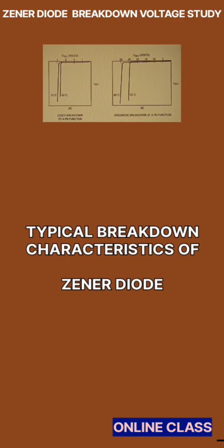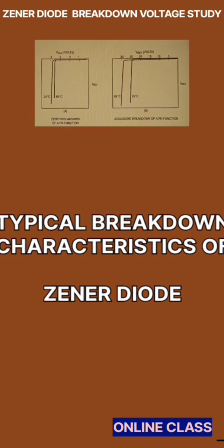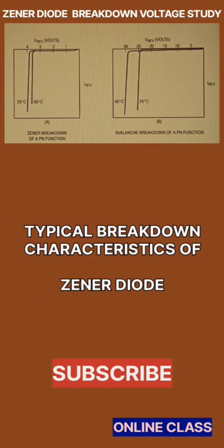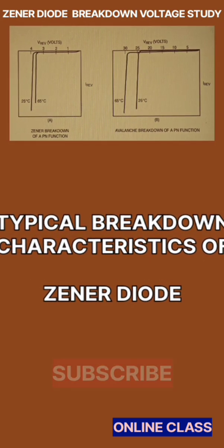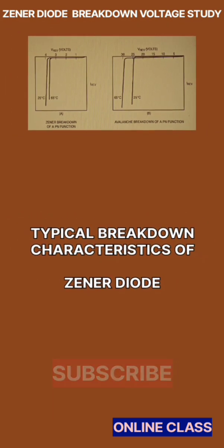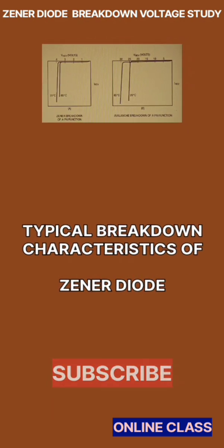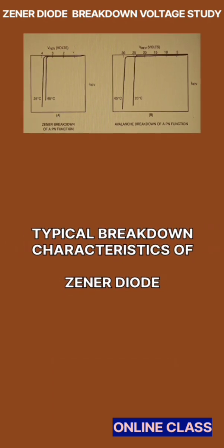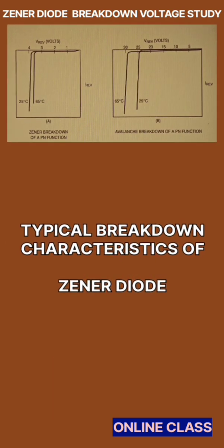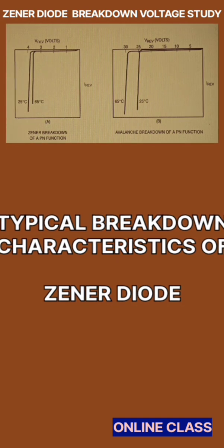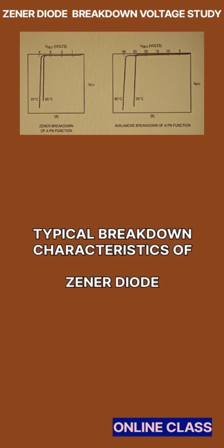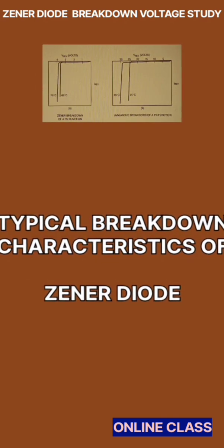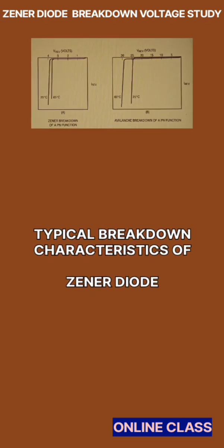When two different resistivity p-type materials are placed against two equally doped low resistivity n-type materials, the depletion region in the low resistivity p-type material will be smaller than that in the high resistivity p-type material. Furthermore, in both cases, only a small portion of the resulting depletion width will extend into the n material if its resistivity is low compared to that of the p-type material. In other words, the depletion region primarily expands into the material with the highest resistivity.